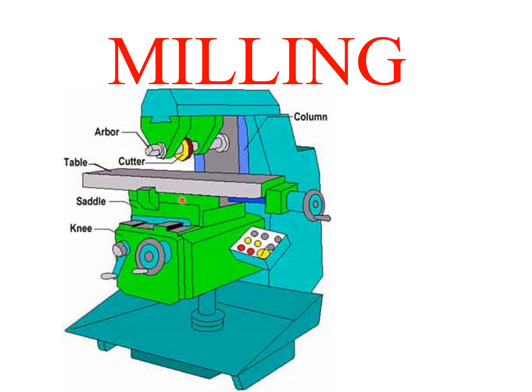The speed at which the piece advances through the cutter is called feed rate or just feed. It is most often measured in distance per time, that is inches per minute or millimeters per minute, although distance per revolution or per cutter tooth are also sometimes used.